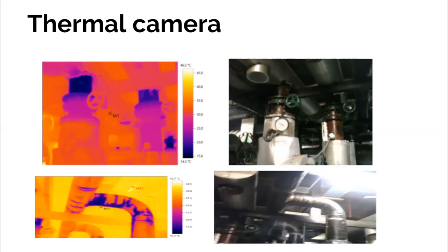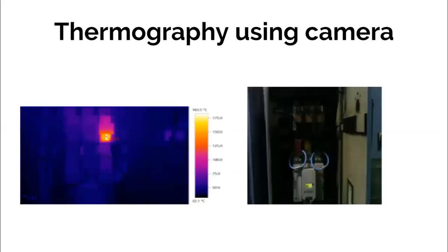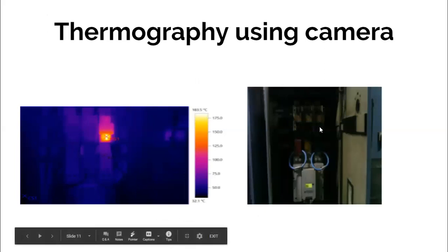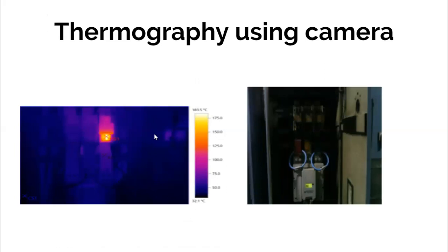When you can make out the temperature distribution, and you are expecting a uniform temperature distribution because that particular component is insulated, and when you are finding an abrupt small temperature over there, small spots over that, then you can identify the problem, and then you can take corrective actions. So this is a very useful tool for doing an energy audit. This kind of reports you can generate, which is called a thermography. So by using this camera, you generate a thermography report, and you can make a presentation to the company for which you are doing the thermography, and tell your suggestions.